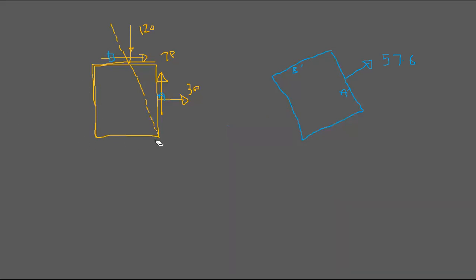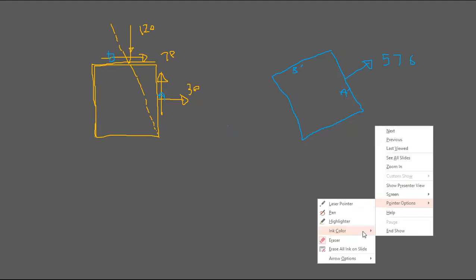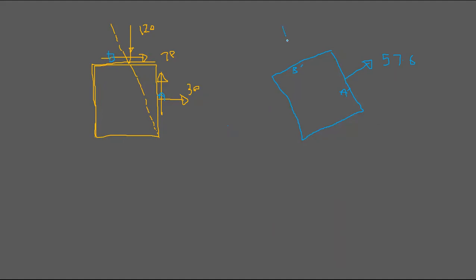If you want, you can draw these two walls as well. So this is in compression, 147.6. So you can see if you rotate it 21.5, right? So your maximum principal stress state is achieved, right? So you can see this 57 point is larger than this tensile stress, and 147.6 is larger than this compression, right?